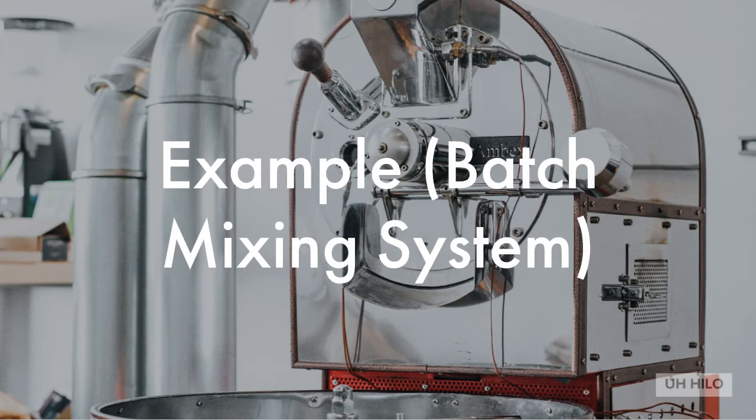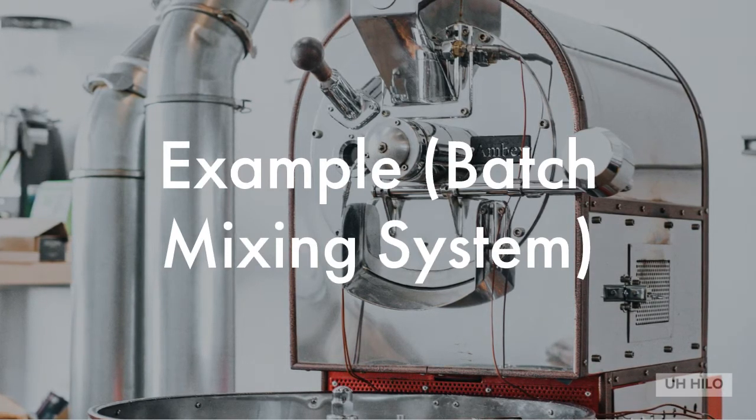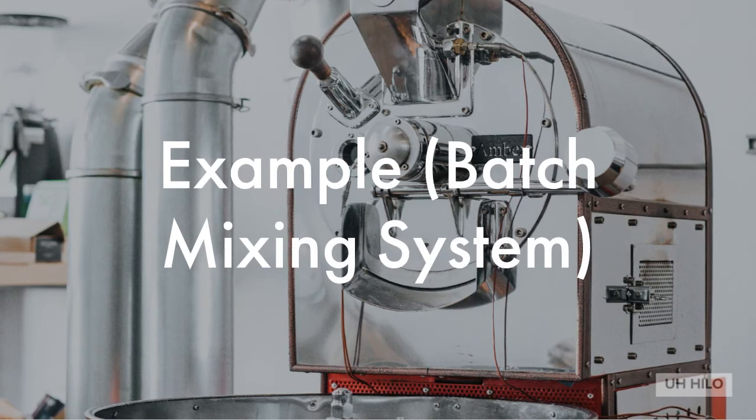There are 3 movable fluid sensors in the tank that can be set to turn off the respective valves for the first ingredient alone, for the first and second, and for all 3 ingredients. The switch is used to select either a 2 or 3 ingredient option.